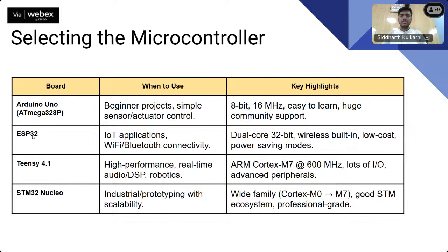But for most use cases, ESP32 should be more than enough. It is very cheap as well. You can get it for 400 rupees and you can do a lot of stuff. It gives you wireless connectivity. It can control multiple sensors, motors, screens simultaneously. So for most of your use cases, ESP32 should be fine. But for many simpler use cases, you can look into Arduino, ATmega328P and other smaller microcontrollers as well, because those will be more sustainable and easier to program, also cost effective.